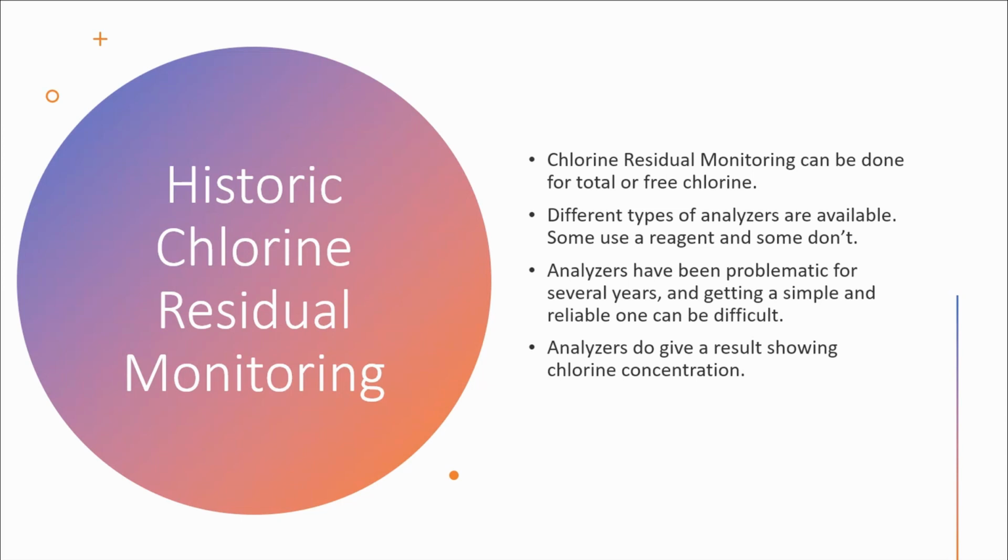It's amazing how much water chemistry can affect that part of the analytics. Chlorine does weird things in different types of water. You pull from a different well, all of a sudden your whole chemistry changes in the plant. That's one of the things we've seen with some of our tests. Yeah, different times of the year, the water department will pull from different wells, which changes some compound, some chemical in the water, whether it be more manganese or what. And it completely changes the reactivity of the chlorine. Yeah, for those water systems.